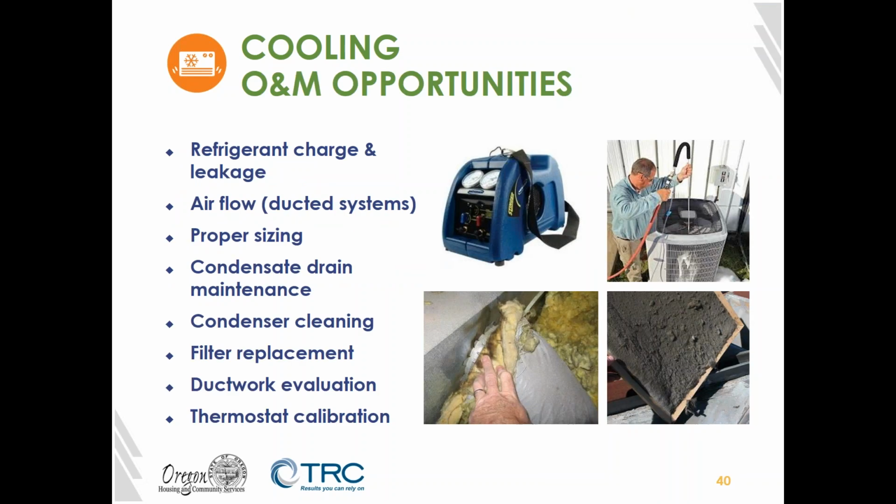So O&M opportunities for cooling systems are many. Refrigerant charge and leakage testing is really important to ensure that our system is properly charged and can operate effectively and efficiently. A refrigerant is really like a Goldilocks situation. You don't want too much and you don't want too little. You want just the right amount of refrigerant, and that's how your system is going to perform its best.